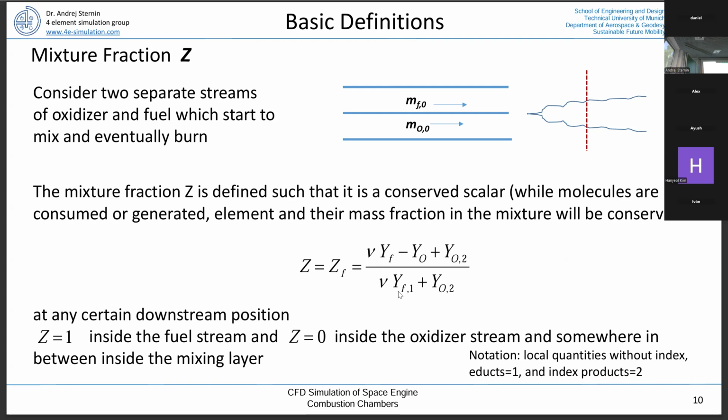And as I already mentioned, in a large number of combustion applications we can assume temperatures are sufficiently high that we reach chemical equilibrium, meaning the reaction is very fast, meaning the flame is very thin, similar to a shock wave. Then we can say there's one position where it's cold and the other where it's hot and burning. That makes the model simpler.